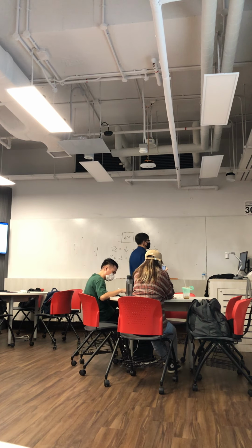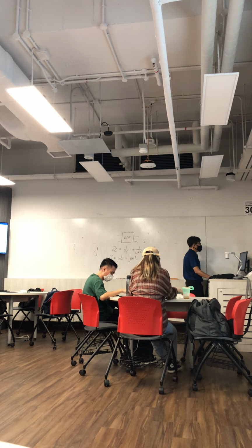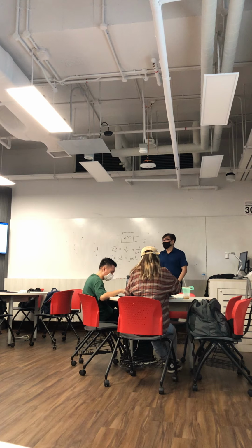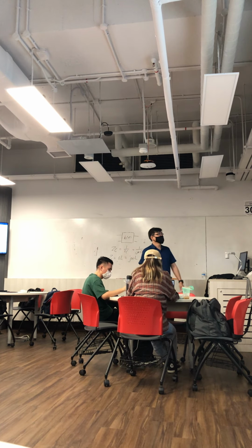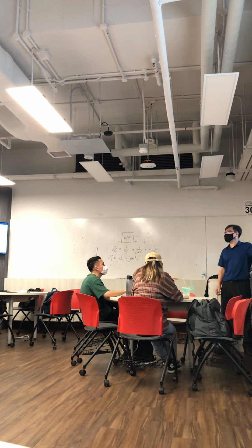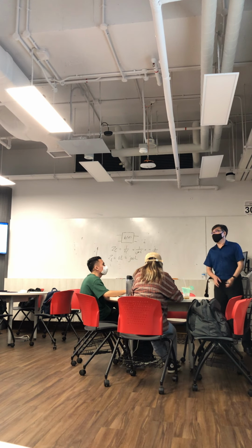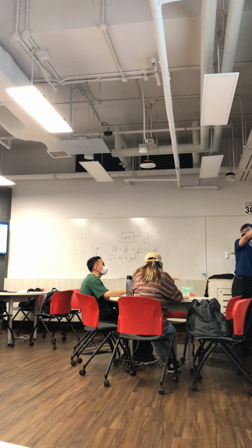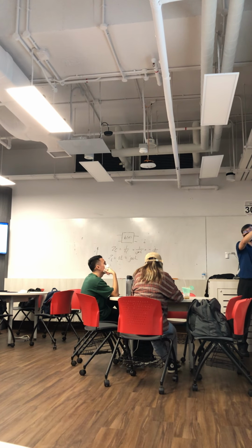Okay, so I just wanted to show you the Laplace transform. Now, forget about this one. Here I'm trying to show that when I solve it in the time domain, I also get the same equation. If I'm interested in the Laplace transform of this voltage, with this as the input, the voltage gain or voltage transfer function will be this over this, right?